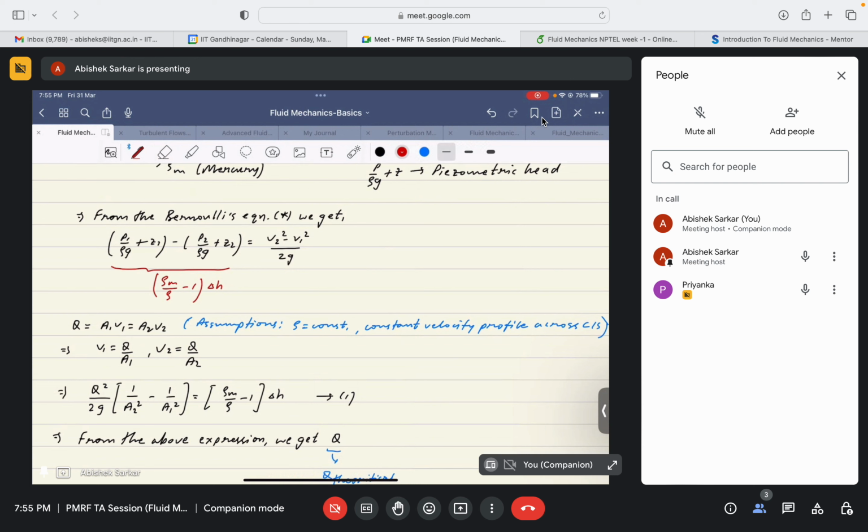If storage is the case, then why take into consideration the frictional losses? Even if there were no frictional losses, and if you are saying that water would have got stored in the municipal pipes, then there's no requirement or role of frictional losses to reduce the mass flow rate at the exit. Even if there are no frictional losses, and if the water is getting stored within any section of the pipe, then it will eventually get stored, right? There's no requirement of losses because of viscous effects, right?